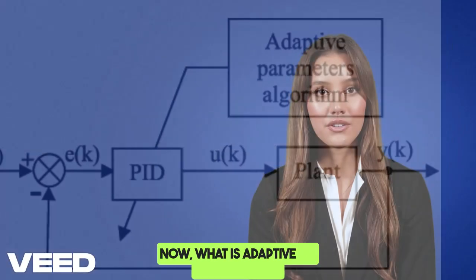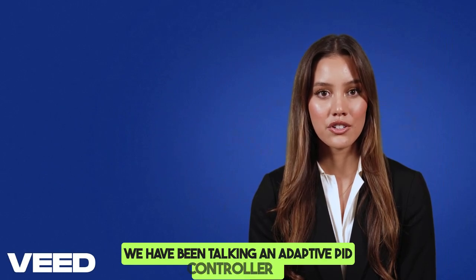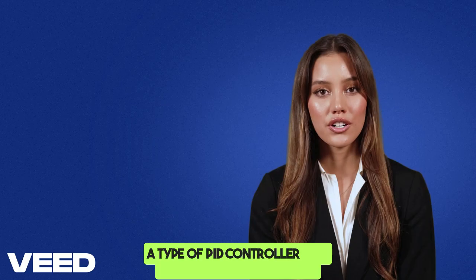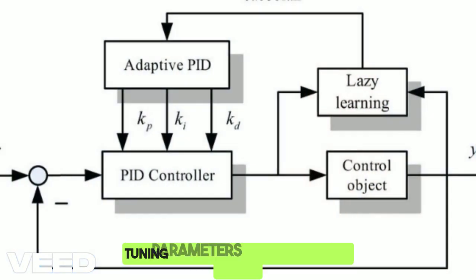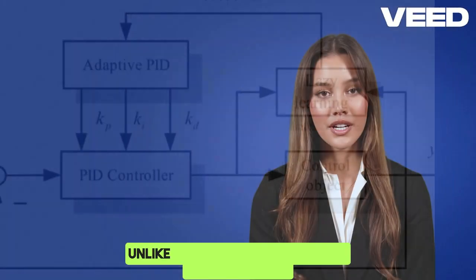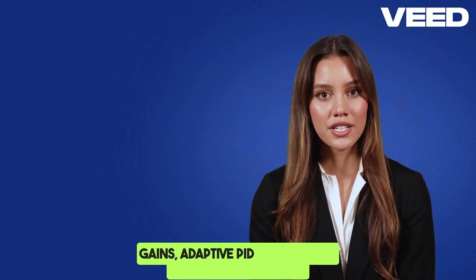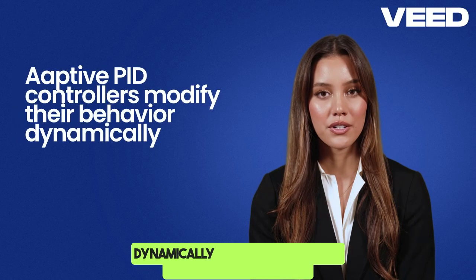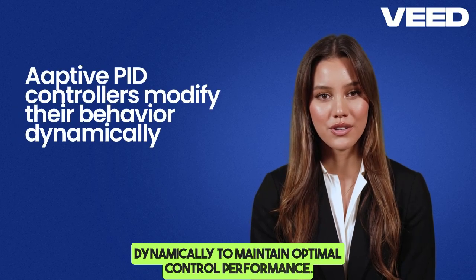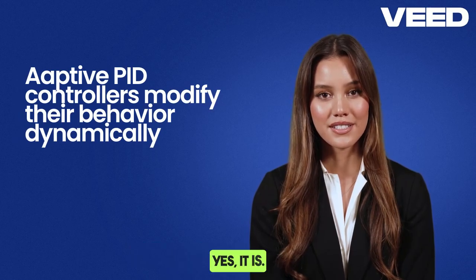Now, what are the adaptive PID controllers we have been talking about? An adaptive PID controller is a type of PID controller that automatically adjusts its tuning parameters, P, I, and D settings, in real time based on system changes or external disturbances. Unlike traditional PID controllers, which have fixed gains, adaptive PID controllers modify their behavior dynamically to maintain optimal control performance. Sounds interesting? Yes, it is.